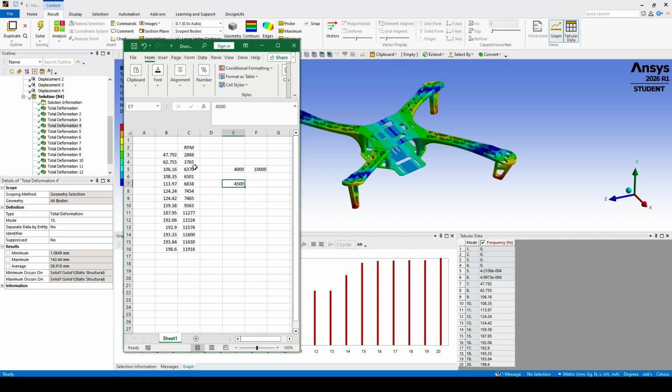In this case, I can see that I have many resonances occurring at 6,300, 6,500, 6,800. They are all near each other. So we have to prevent any speed at these RPMs, between 6,000 and 7,500. I would recommend not using any speed in this range.